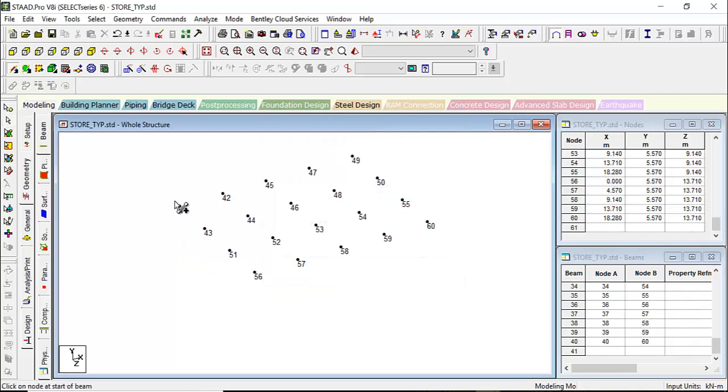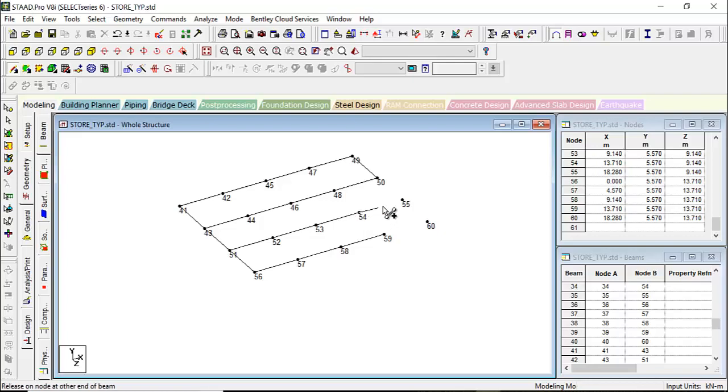Now let's go for add beam. Individually we can go for add beams, just go on adding beams. Now the thing is that on the roof slab we need to provide beams everywhere, but in the plinth beam we need not provide because there is already a ground support. Though we design for a frame structure, there are no floor loads on the plinth beam. So why waste our cost on that? So let's put these things together.